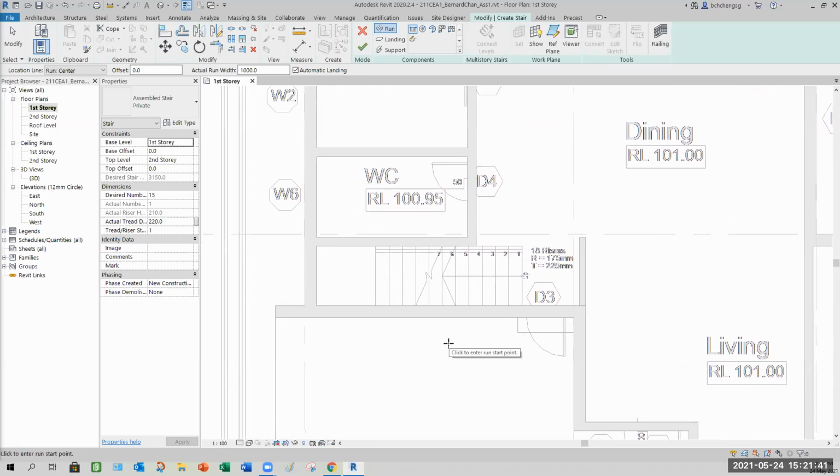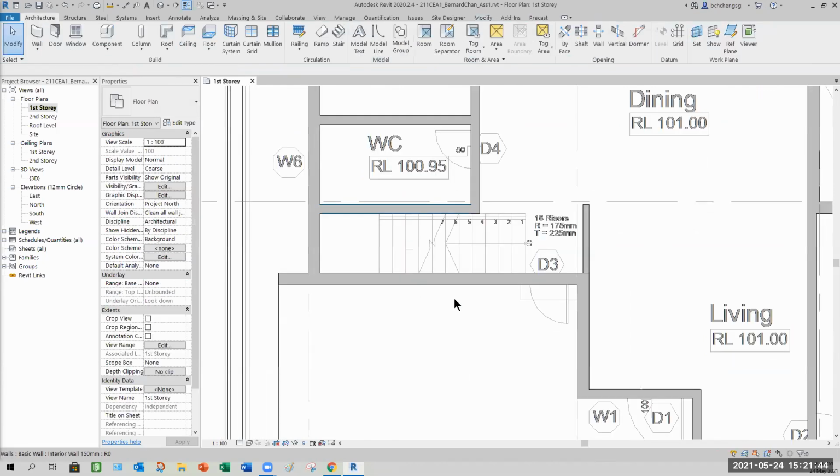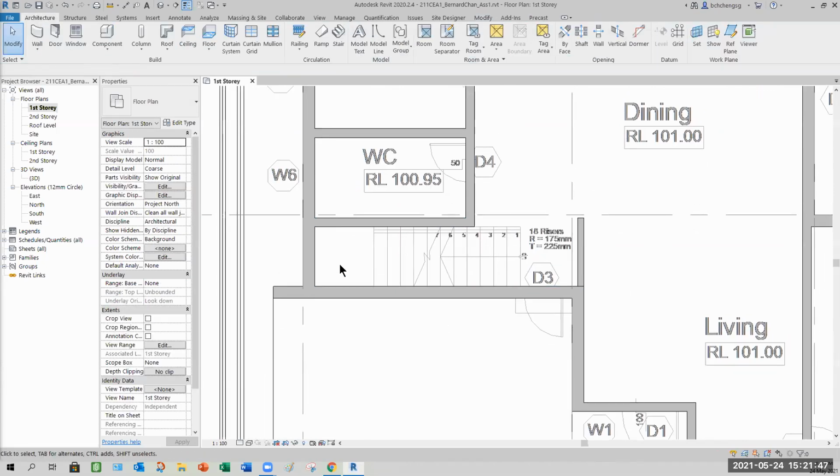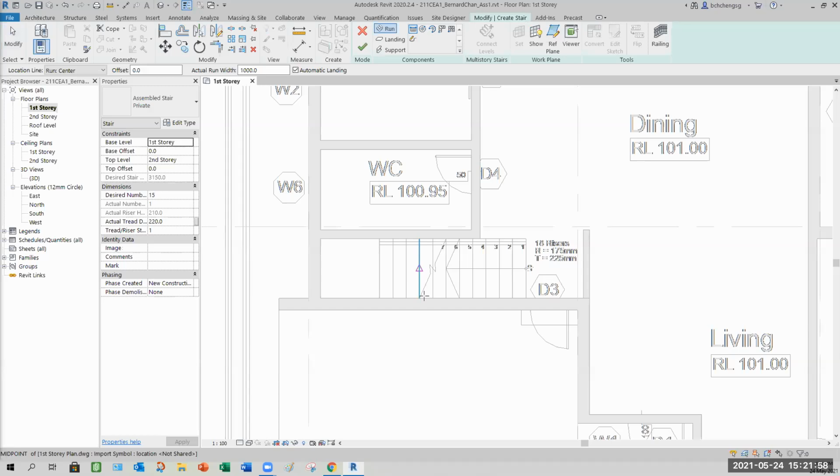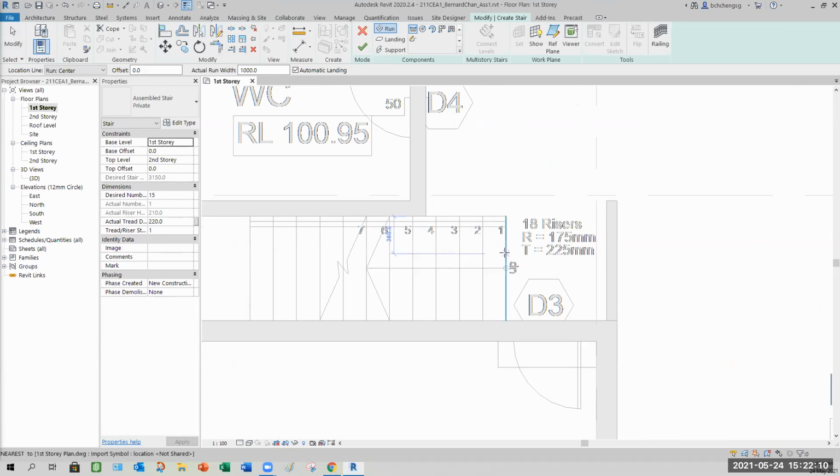Okay, now you can see. Let me close this. So you get your tools for stairs. As a designer, you need to create stairs that must comply with the local code. That's why just now I was explaining this. Residential here, the minimum for the tread, meaning this width, can be as low as 225. Default is 250. Then the riser highest is 175.